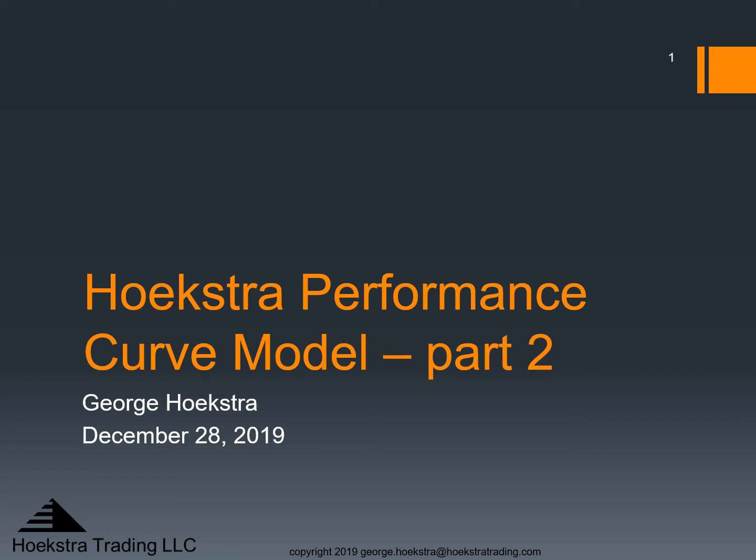This is the second in a series of short videos on the Hoekstra Performance Curve model for gasoline desulfurization. The key to optimizing a gasoline desulfurizer is to maximize desulfurization and minimize octane loss. That's why we focus on a single curve of octane versus product sulfur, and we call it the performance curve.